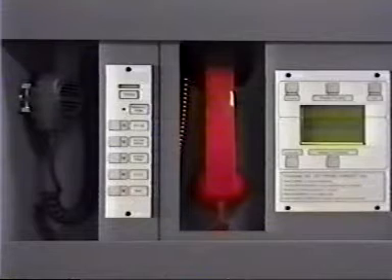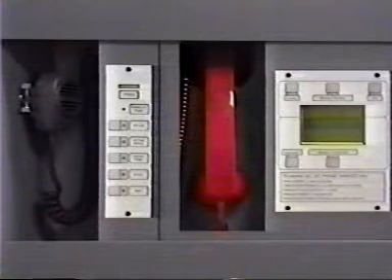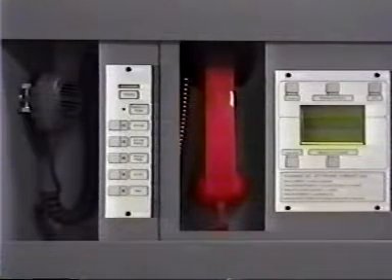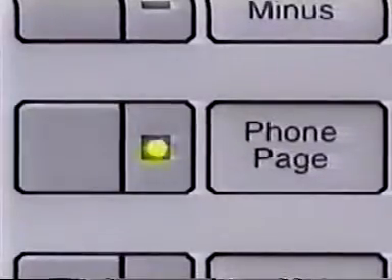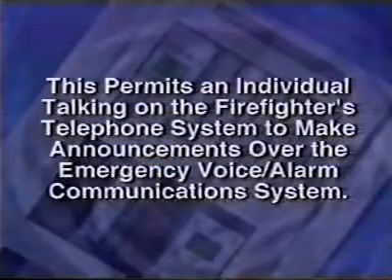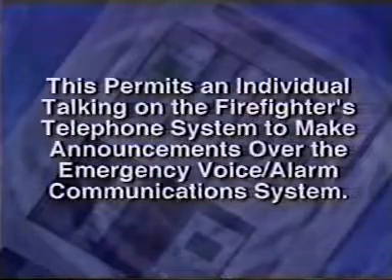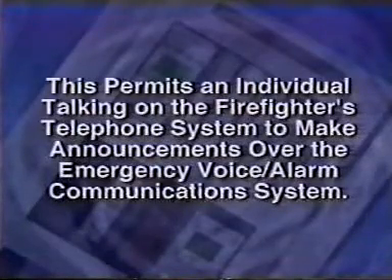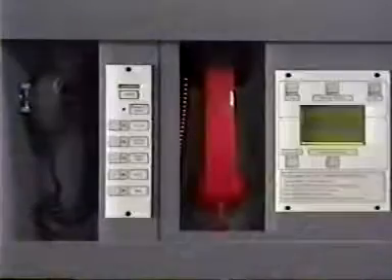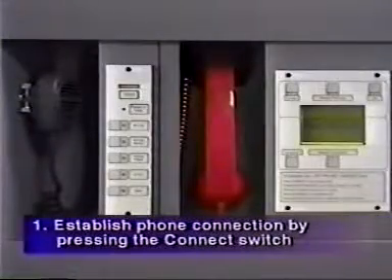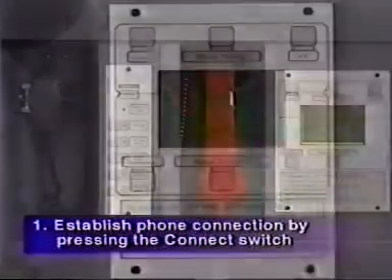The 3 FTCU may also be used in conjunction with the 3 ASU phone page switch. Pressing this switch permits an individual talking on the firefighter's telephone system to make announcements over the emergency voice alarm communication system. The first thing you'll need to do is establish a phone connection with the 3 FTCU by pressing